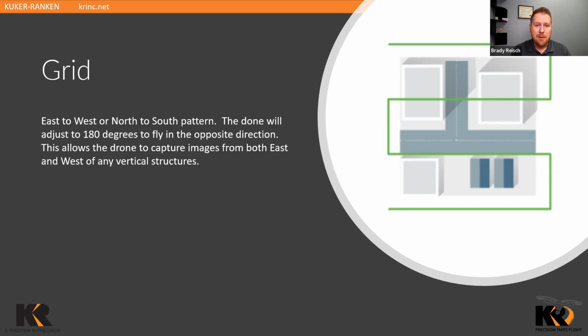With this, traditionally photogrammetry requires somewhere between 70 and 80% overlap, while LiDAR, depending on the system you have, could be as low as 20%. So this is where your efficiency really kicks in using that LiDAR system. So grid pattern, you're just moving back and forth.